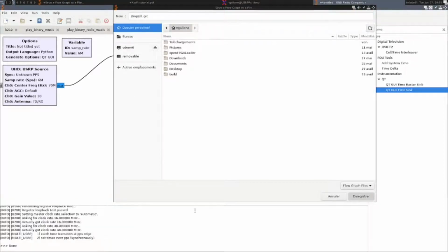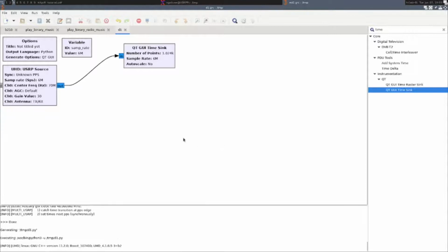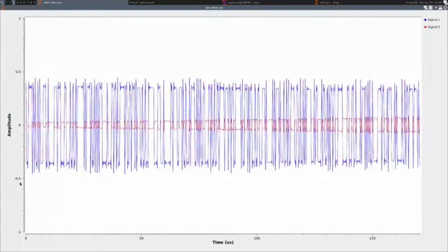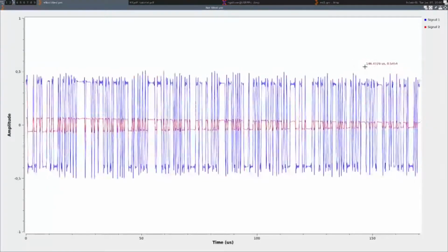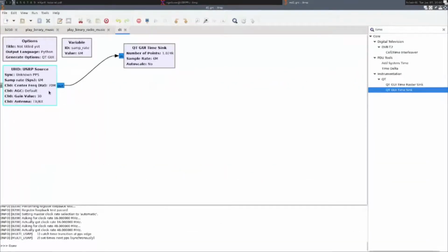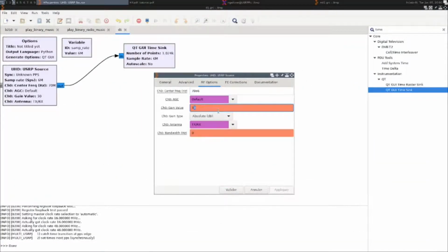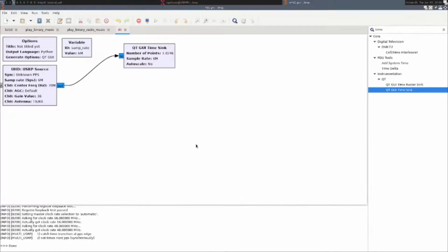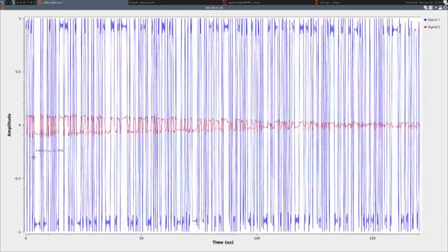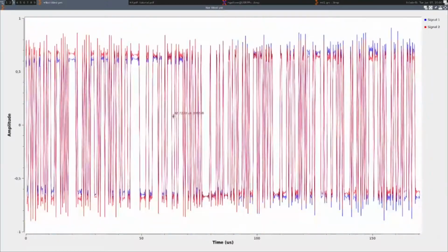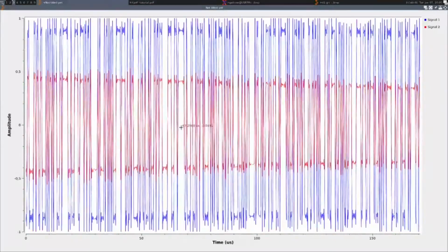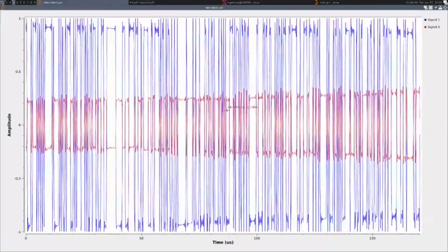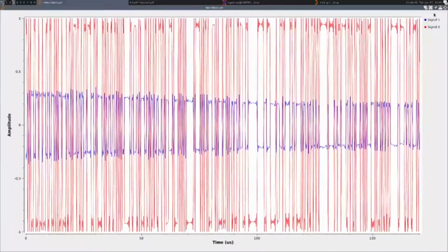the radio frequency path? So we execute this flow graph from the B210, and we see here that we have an amplitude which is about plus or minus 0.5. So we can gain a little bit to try to fully use the accessible range. Say we gain a factor of 2, so that's 36 dB over here. And if we run this, we should be using the full scale of the analog to digital converter. So surely enough, here -1 to +1, and you see the drift, so the phase drift appears with the I and Q coefficient fluctuating slowly at the rate of the frequency difference between the two clocks.